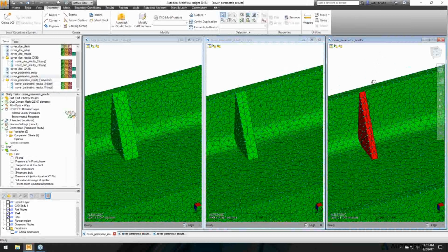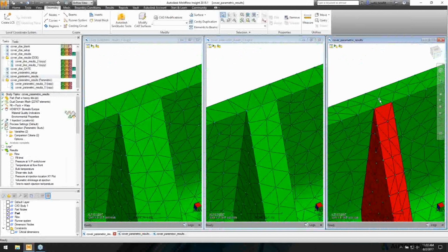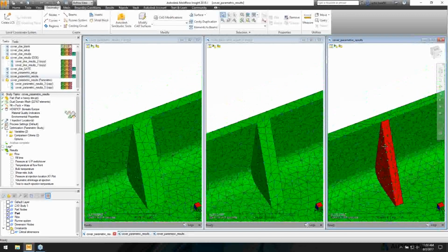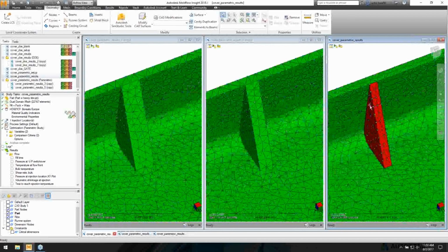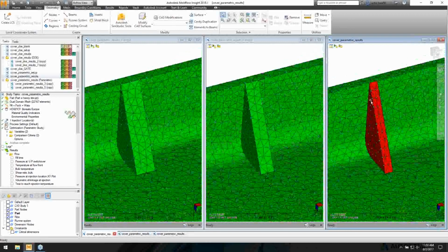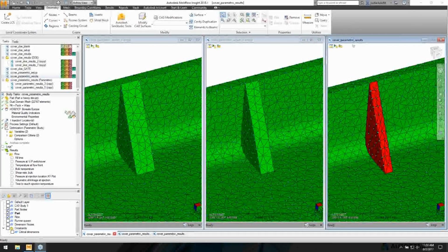You can see if you zoom up on that edge that the original had an extra node here, so it remeshes, and it doesn't always mesh in the exact way, so it probably is not going to have the exact same node. So I don't think you can use node lists because it remeshes when you make those modifications. Great, thanks, Justin.